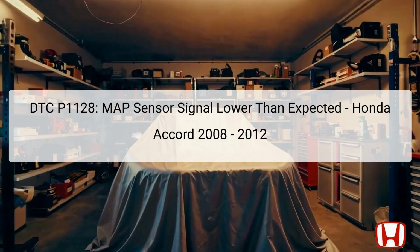The diagnostic trouble code DTC P1128 indicates that the manifold absolute pressure MAP sensor signal is lower than expected. This code specifically refers to the MAP sensor's output voltage being below the normal threshold, which suggests potential issues within the intake air management system. The MAP sensor plays a vital role in the engine management system as it provides essential data regarding the amount of air entering the engine.